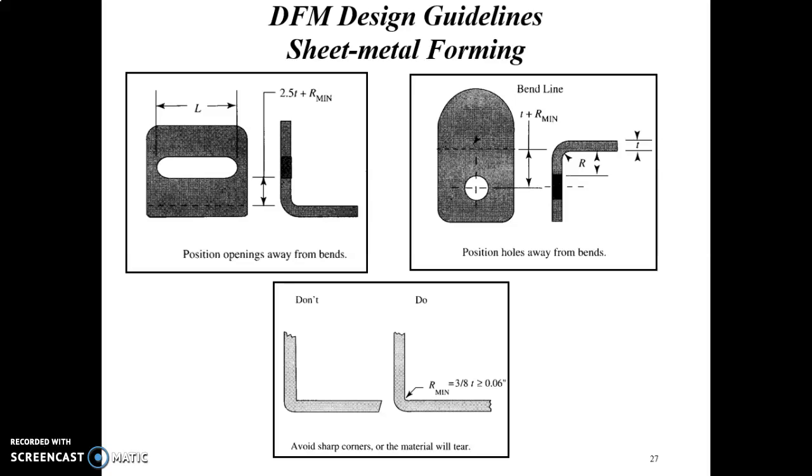Bending is actually a process whereby a force is applied to sheet metal which causes it to bend at an angle and form the desired shape. A bend can be short or long depending on what the design requires. Basically we use a press brake machine, so that the bending can be automatically or manually loaded.